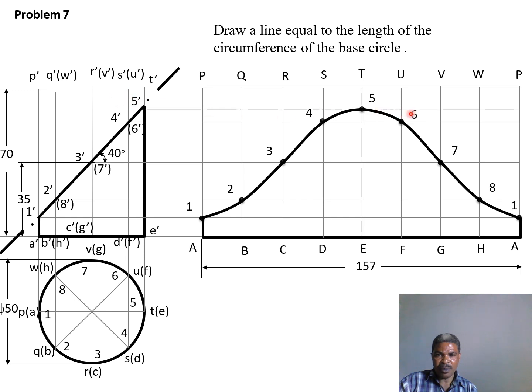But one thing very important to note, the total length for our development, that is A to A. How do you get it? You have to remember that we said it is pi d. The circumference for our case will be regarded as pi d, or 2 pi r. You obtain the total length for our development.